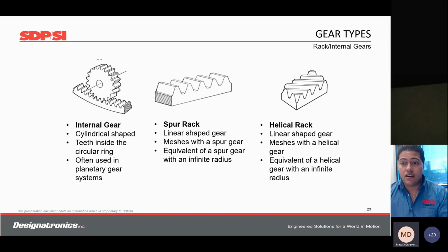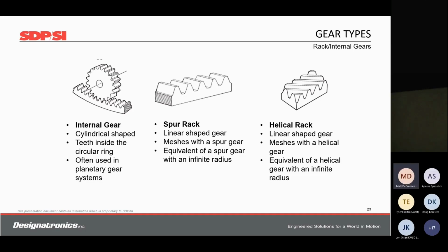So another type of gear that we want to talk about is the internal gear. So internal gears require very accurate outside diameters or banking surfaces to manufacture and assembly. If your internal gear is already incorporated into your housing, you don't really have to worry about that. But if it's not, you're going to need very accurate surfaces. And I'm talking about 2/10 and very concentric, about 5/10. 0.0005 of an inch of accuracy on that run out.